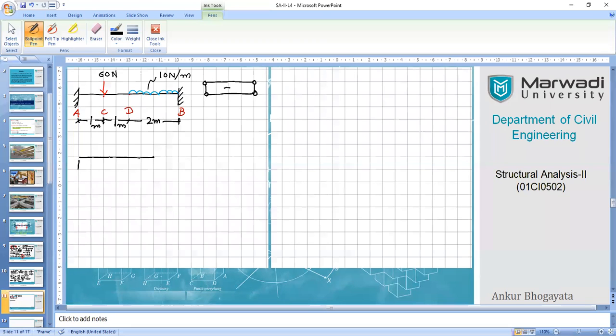I'm just explaining why we should not first obtain the reactions. So right now we have applied the forces. You can see that it's now a typical MOS kind of problem, mechanics of solids, where if you take moment of all the forces about this point, you can get the reactions definitely. But if I don't want to do it at the beginning, right?